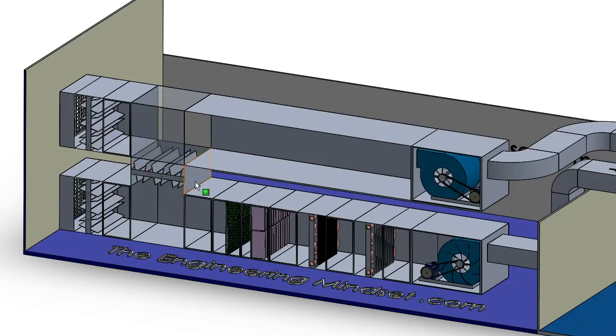Now, you don't have to have this here. You could have that duct straight across and this also duct straight across, so that these two are not connected. That's certainly the way in the past it was achieved, but it's really expensive to do that. So if you imagine, if you didn't have this connection here, then all that air that you brought in would have to be filtered, heated, and then cooled.